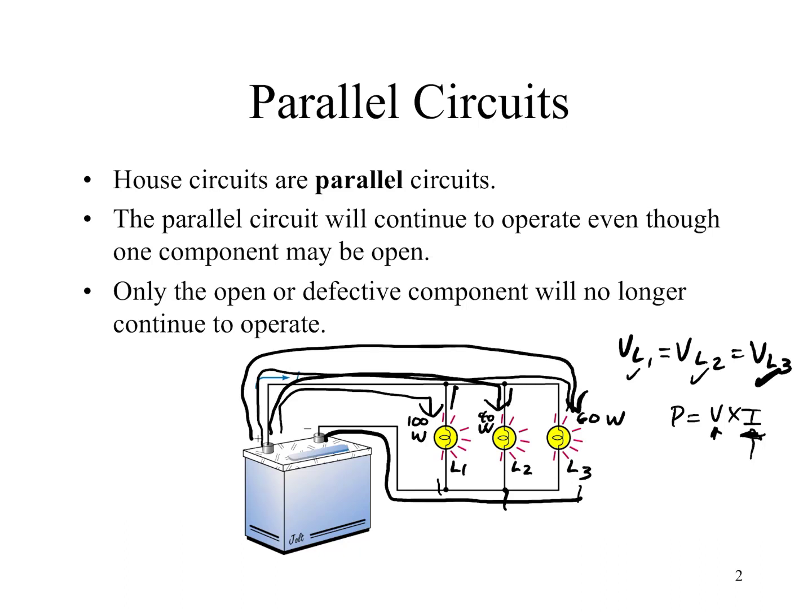And if that's the case, then instead of a voltage divider like what we had in the series circuit, where the E total value is being divided by the loads, in this case we have I total being divided by the loads such that I total equals I1 plus I2 plus I3. So this is where a purely parallel circuit is called a current divider.